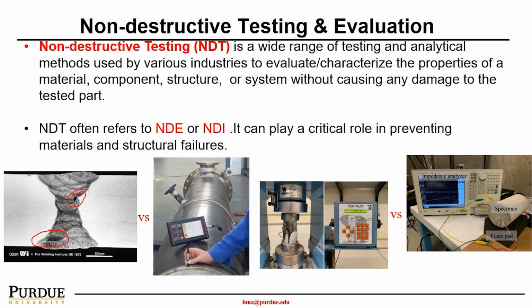So when we're testing to identify welding defects in service, rather than doing this type of image processing, we could use ultrasound, as shown here. By sending an acoustic wave and analyzing how the wave propagates and reflects, we could get an image of the welding quality, whether there are any voids or not, right?